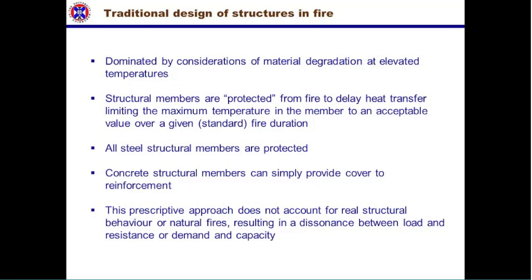So all steel structural members are protected typically, but concrete buildings can get away with just providing a little extra cover to the reinforcement for a longer fire. This sort of approach, which is a prescriptive code-based approach, does not really account for the true behavior of structures in natural fires, in real fires. So this, to our mind, results in a dissonance, a disagreement between load and resistance, demand and capacity.